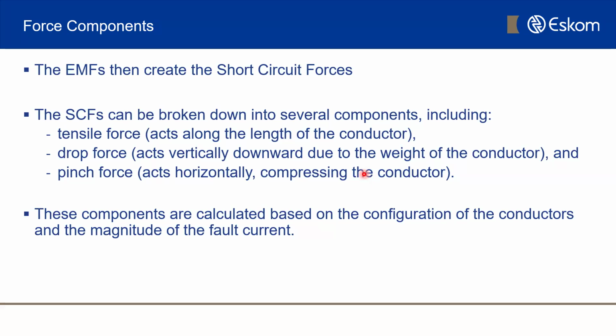Three of them cause the most effect on our structure, and that's the tensile force. And this tensile force acts along the length of the conductor, which, as you know, because it's spanning between two gantries, already has a tensile force. So that increases the tensile force.